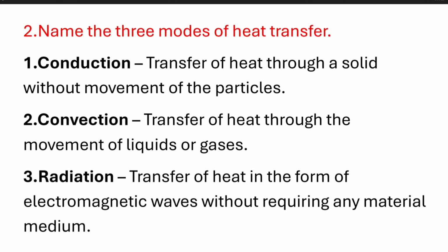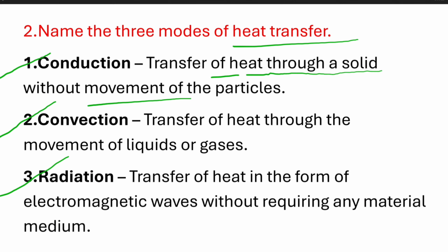The next question: name the 3 modes of heat transfer. The first one is conduction, convection, radiation. These are the 3 modes. You can write only the names. So, if you want to learn what is meant by conduction, convection and radiation: in conduction, heat is transferred through a solid without movement of the particles. So heat will be transferred, but there is no movement that takes place in the particles.